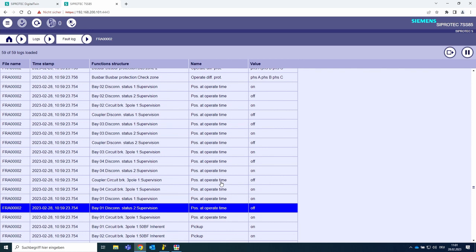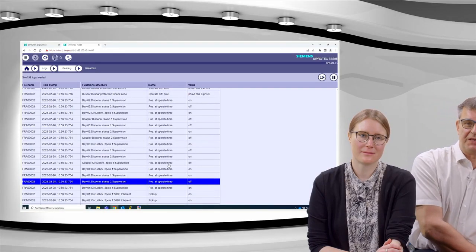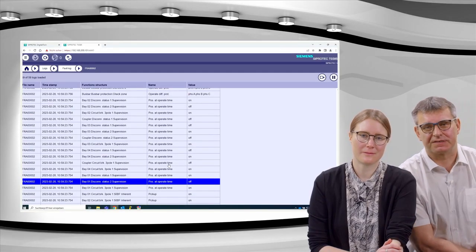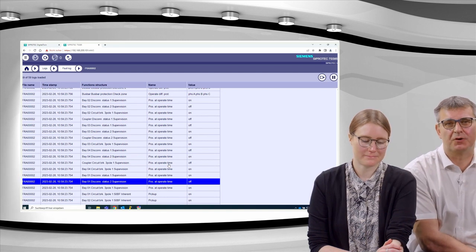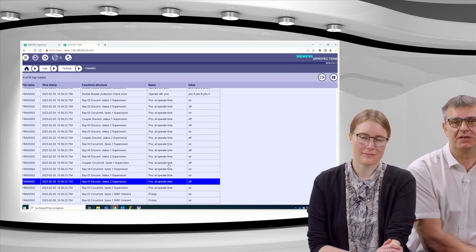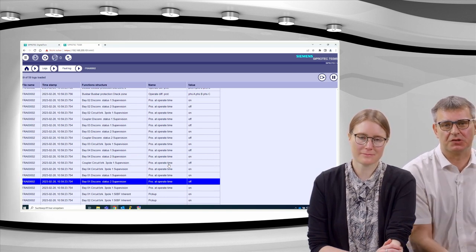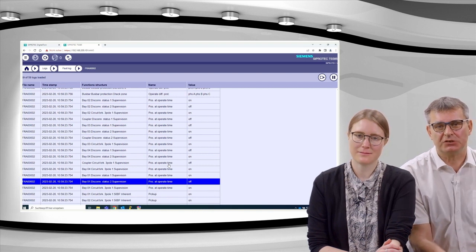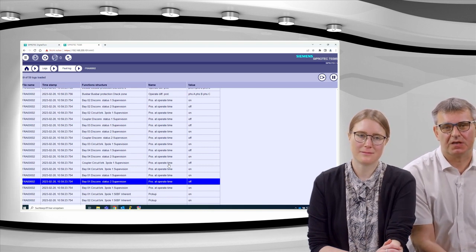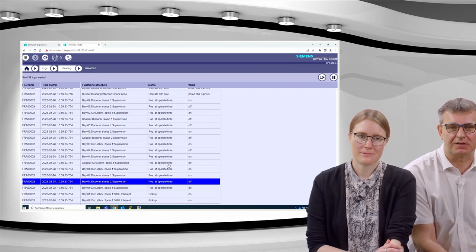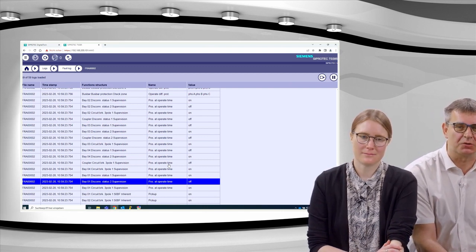Typically, when there's a busbar fault in reality, meaning a whole bus zone has been tripped, the management and operational staff have to work to bring power to all consumers once again, and they will switch the disconnectors to ensure power to all consumers. When this is reached, the analysis of what really happened starts.